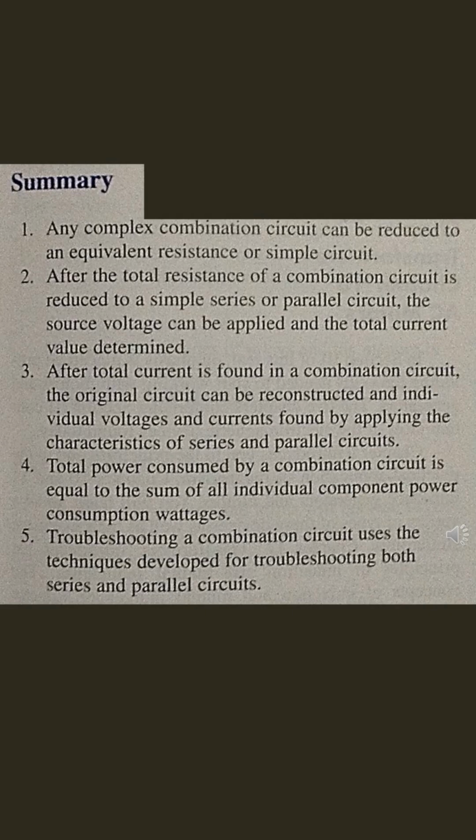Any complex or combination circuit can be reduced to an equivalent resistance or simple circuit. After the total resistance of a combination circuit is reduced to a simple series or parallel circuit, the source voltage can be applied and the total current value determined. After total current is found in a combination circuit, the original circuit can be reconstructed and individual voltages and currents can be found by applying the characteristics of series and parallel circuits.